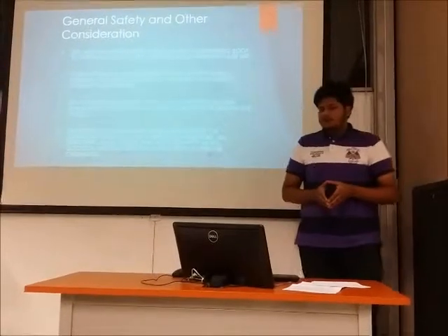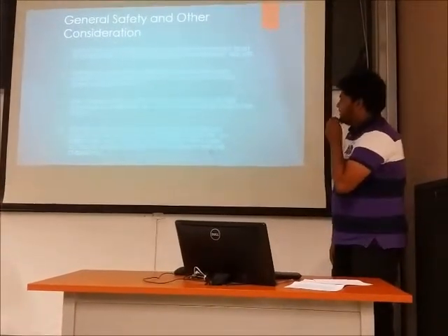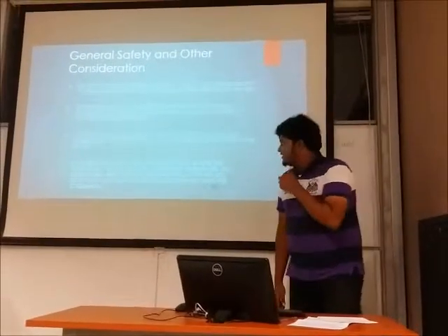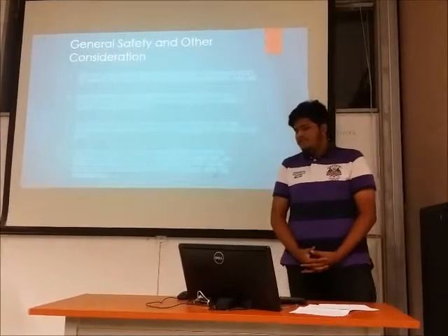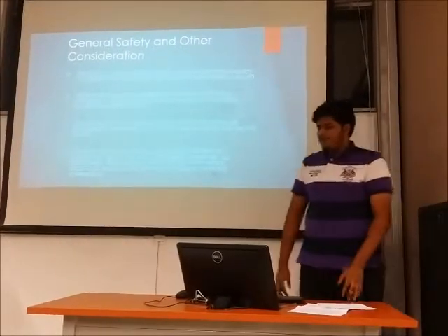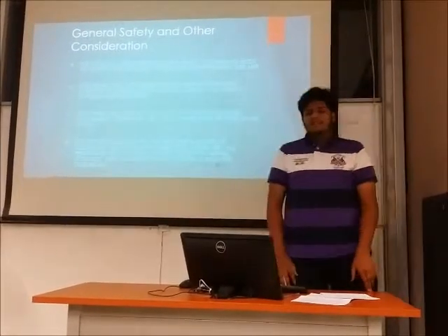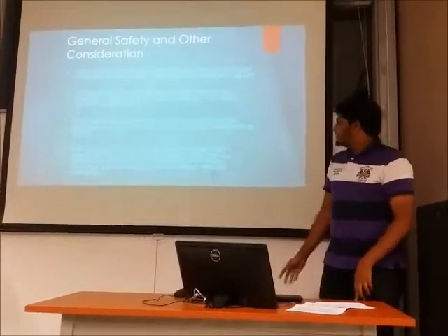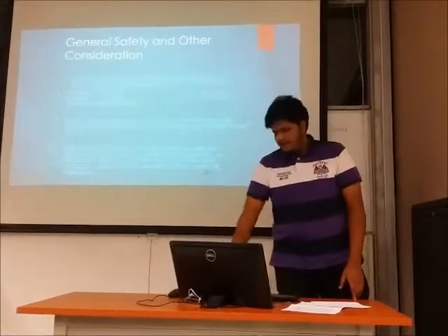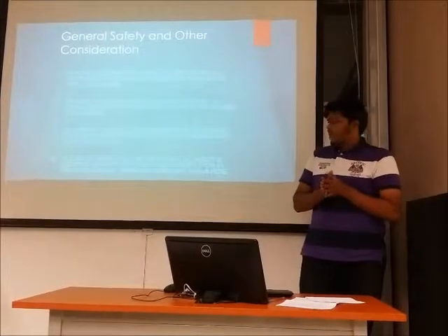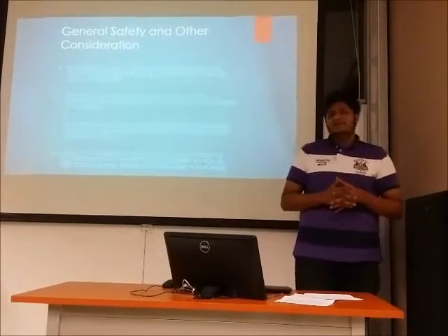The chemical solvents involved in the experiment are flammable. In this case, no open flames must be used in the plant. And this process does have hazards, where some of the chemicals involved are corrosive. Therefore, all personnel and visitors are provided with goggles, masks, and gloves to avoid contact with the chemical. And if you come in contact with any of these chemicals, flush the exposed area for at least 15 minutes with cold water.